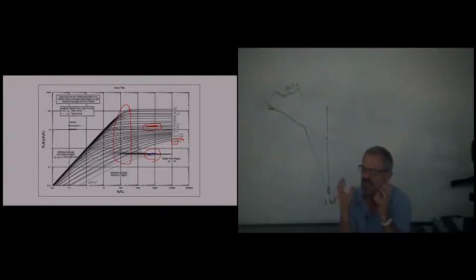We can actually get a simultaneous fit. The separation between the red points and the purple points are fixed. So we can simultaneously fit the data and the derivative data, especially when they're both curves, and without even seeing the middle time region, calculate a perm, calculate a skin, and calculate a wellbore storage.